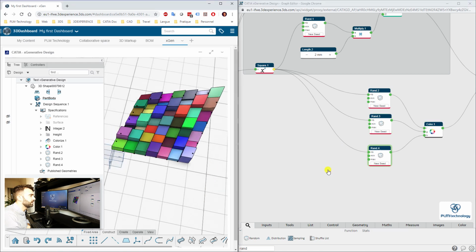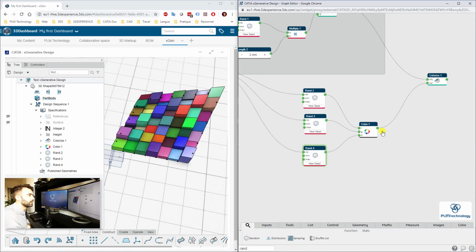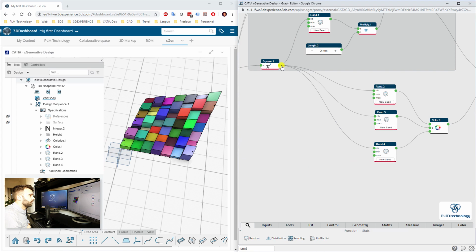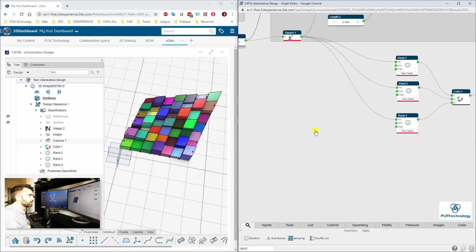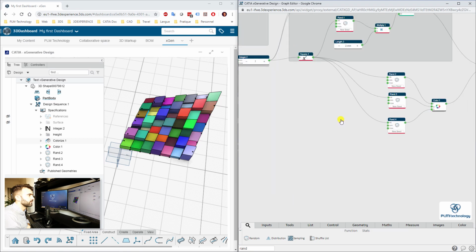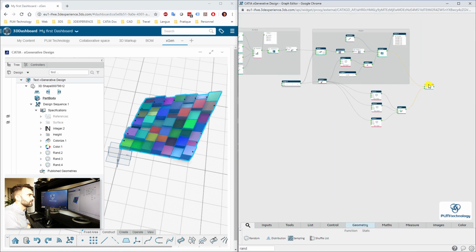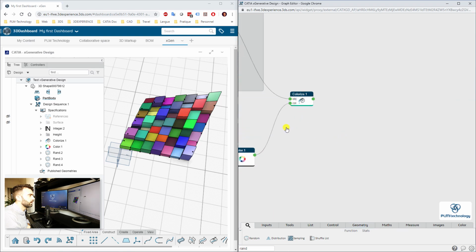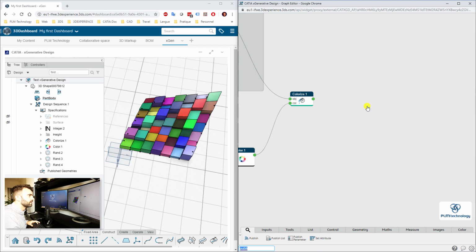And there it is. Now you have created a list of 49 items there, okay, because we have 50 different surfaces there. Oops, I played a bit with the zoom. So now the only thing you need to do, well, actually it's almost done, the only thing you need to do is to publish the geometry. So you need to go there and say publish the geometry.